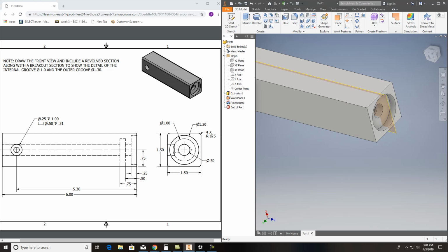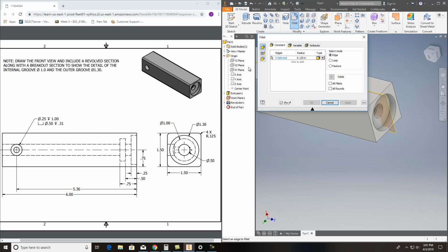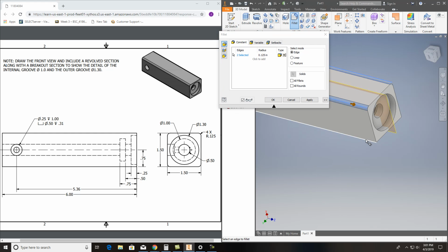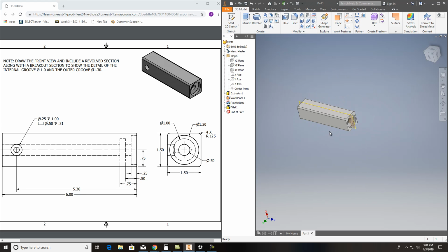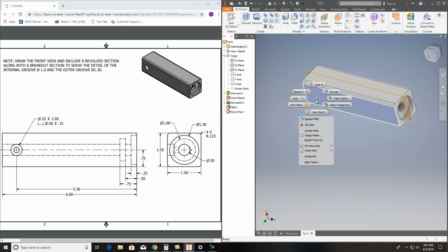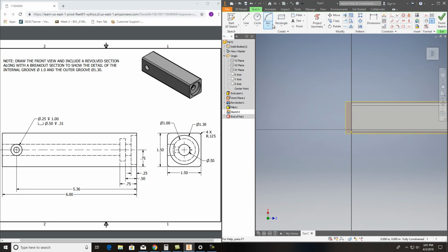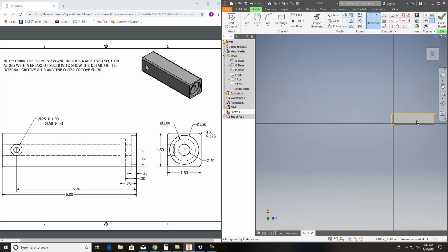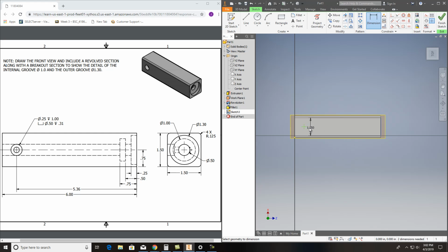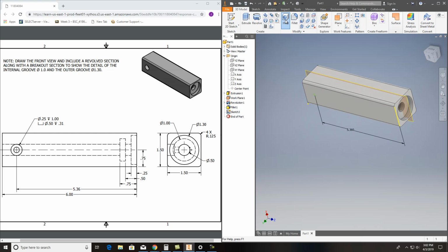It's good. This thing has a radius of 0.125, so hit fillet. 0.125, I select my edges, click on this one, click this one, click this one, click that one on the other side. You got all those in now. And it looks like you got another hole over here, and just new sketch on the edge of that. I want to put me a point in there, and I'll catch the center of this and hover over, dimension it out, and from there to there is 5.36. Finish that up, and then you're going to put your hole command.